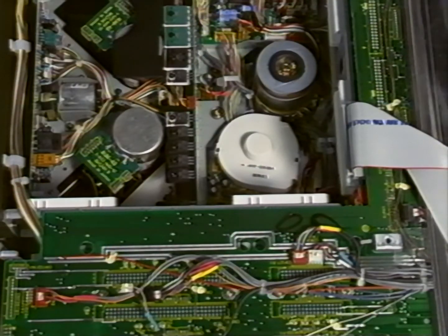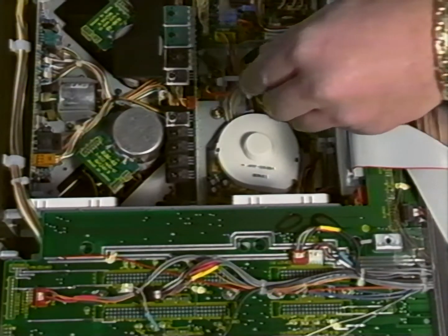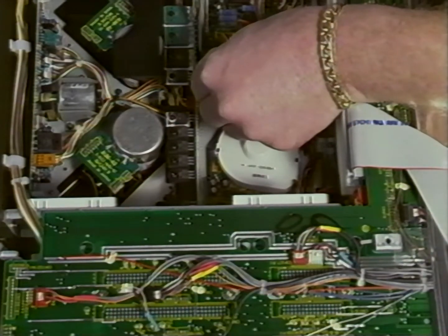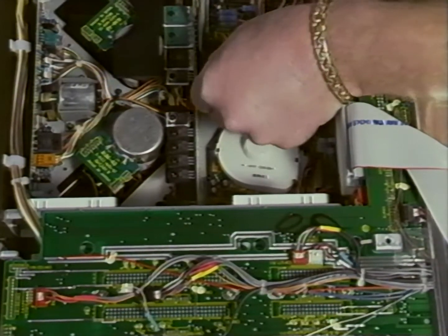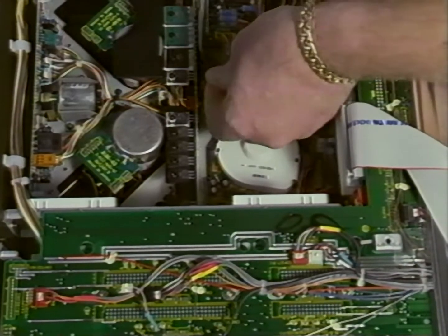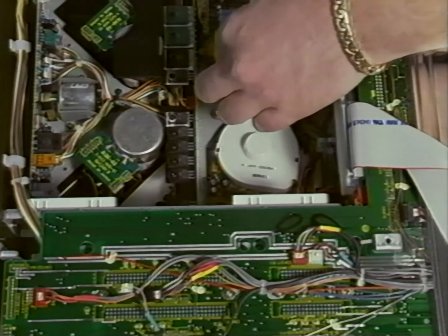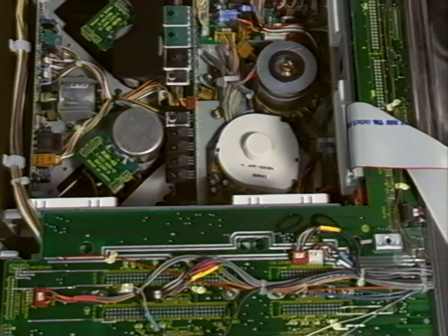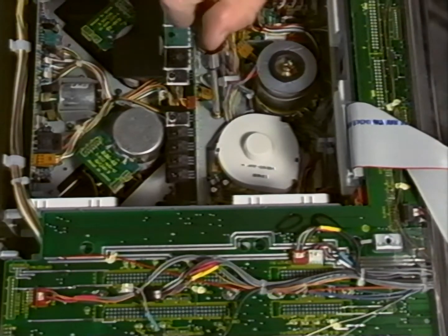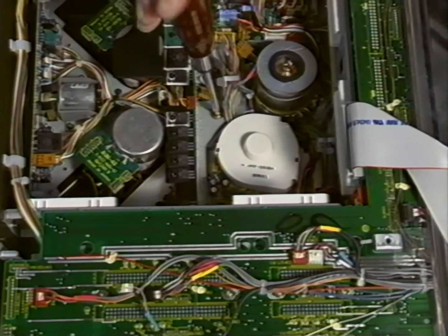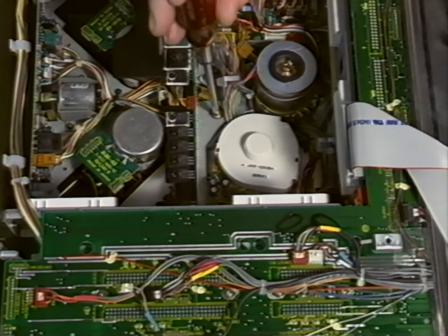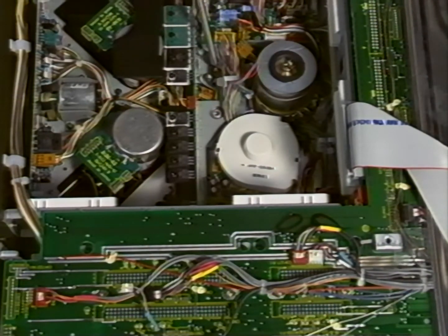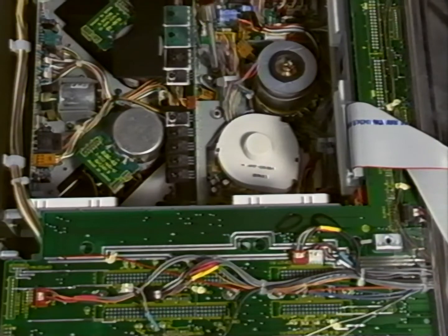To do this, on the bottom side of the machine, carefully remove the connector of the tension arm assembly by placing a flat blade screwdriver on the bottom of the TR18 board and pulling the wires up. This prevents the fragile TR18 board from breaking. Now we can remove the two fixing screws that hold the tension arm assembly to the chassis. With the threading ring removed, the tension arm assembly can easily be lifted from the chassis.